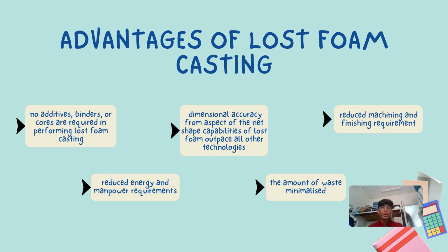I'm going to continue our presentation about the advantages of lost foam casting. First of all, no additive binders or cores are required in performing lost foam casting. Second, reduced energy and manpower requirements. Third, in dimensional accuracy, from the aspect of net shape capabilities, lost foam casting outpaces all other technology.